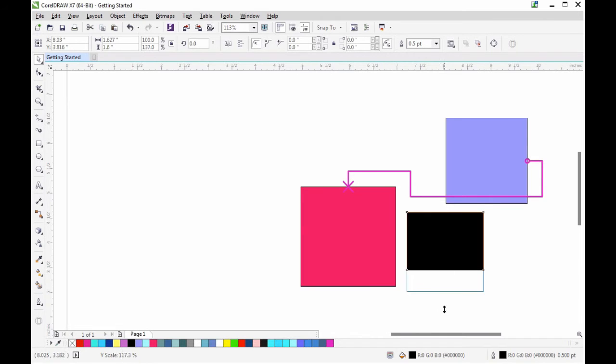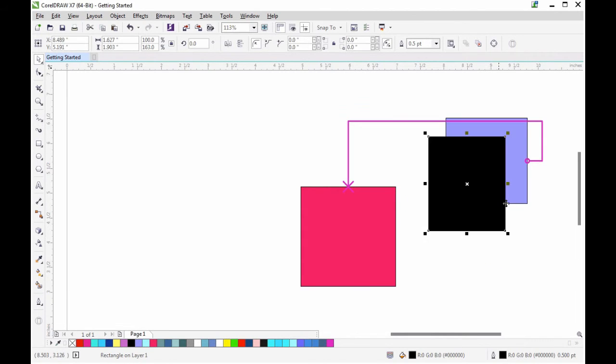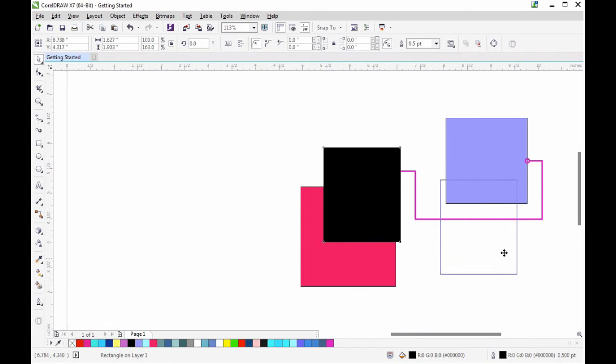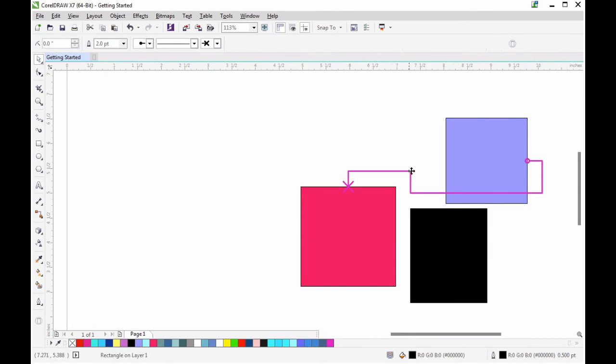Make sure that once you're satisfied with your connector line shape, you've converted it to curves so additional elements within your design don't change your connector line to a path you don't want. In the property bar, you can change the radius of the right angle if you so wish. Or you can use the rounded right angle connector tool instead to have smooth round angles within your connector lines.